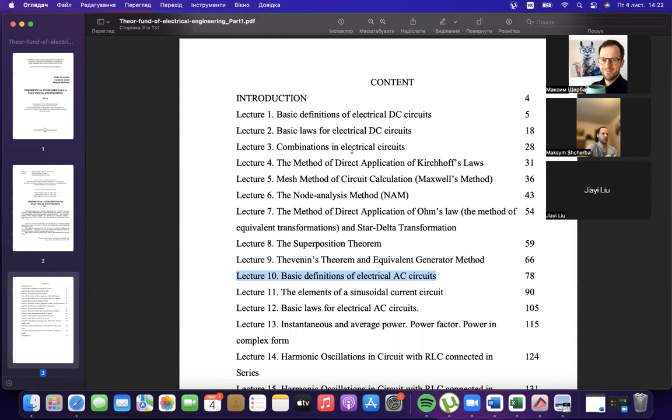Also for complex circuits, we have a couple of methods based on Kirchhoff's laws, either direct application of these laws, or we could transform them into a number of simpler mathematical equations, a number of matrices that we will solve on the computer. It was a transformation of the same laws that we called the mesh method and node method, mesh currents and node voltages. If we want to find all currents, all voltages, all powers in the system, then the more useful will be these first two, node method and mesh current method.